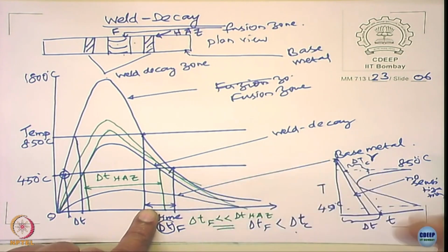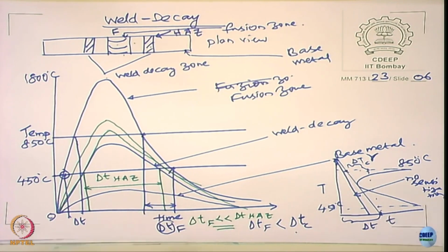What all I am trying to say is that, assume that I am going to take 304 filler wire of 0.3% carbon, suppose I take it hypothetically. Do you think it will not sensitize? It may sensitize. Why?